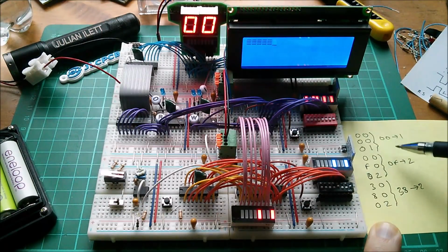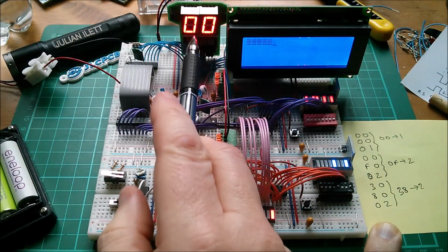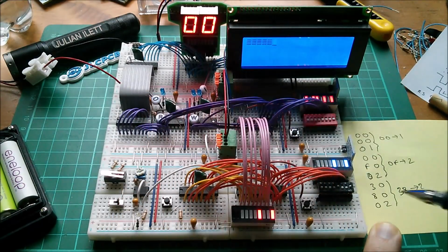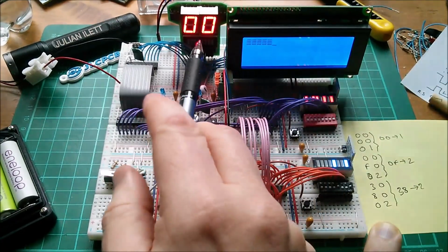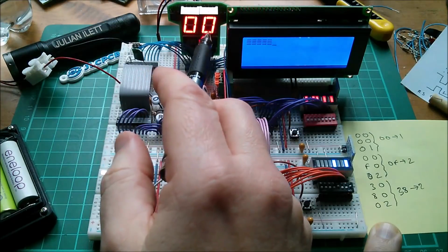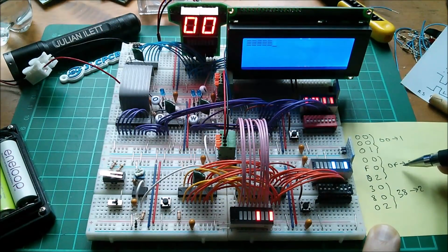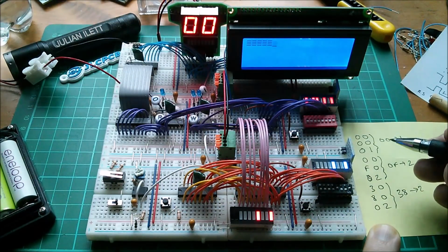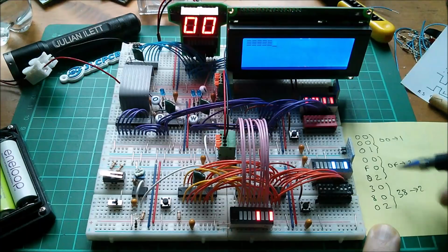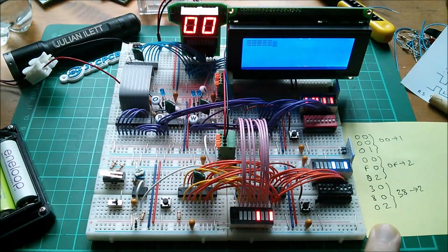So all I'm doing is saying 0, 0 into that register because I want the RS line to be low because I'm sending commands. When I send data, I actually want that least significant bit, so this would say 01. I want that to be high because I'm sending character data. But for the commands, which are 0F and 38, I can't explain what those are. I probably did in the previous video. I need to send those as commands to device 2, being the LCD.